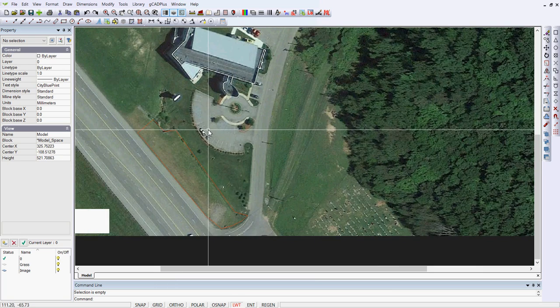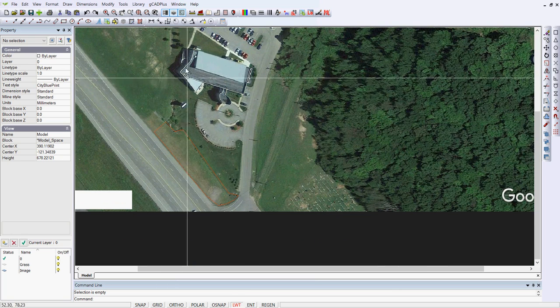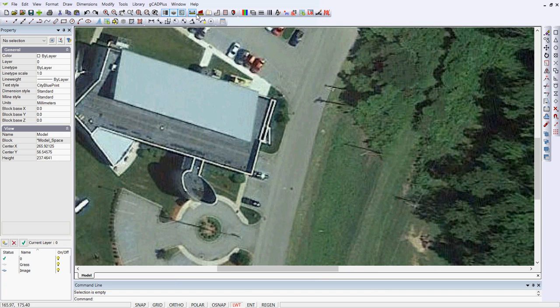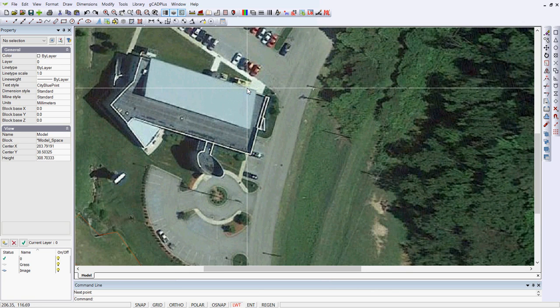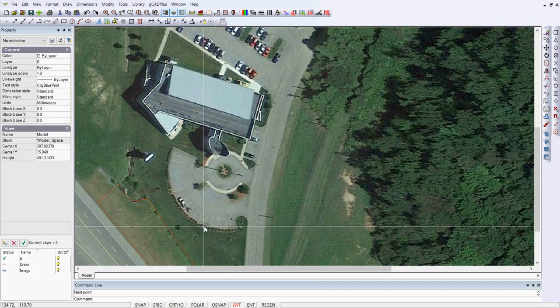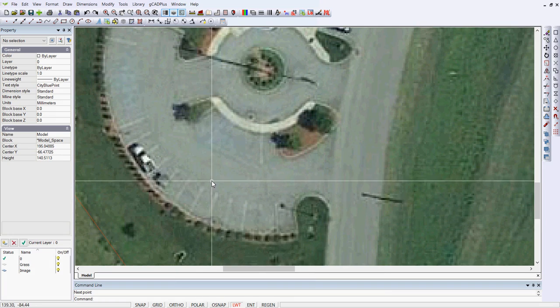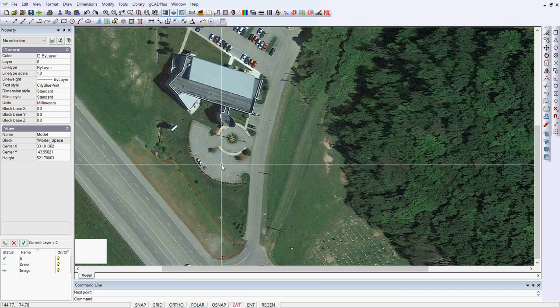You can see a vehicle and trailer has been moved in on that area. We could then draw the footprint of the house, and as you're drawing on top of the image, it's a good idea to put those on separate layers. Let's just check, using our distance, the length of the average vehicle, 15.8 feet in an average US vehicle, and I think that's reasonable. We could probably find somewhere the dimensions of a standard car parking area in the US, just to confirm that we've got things scaled correctly.